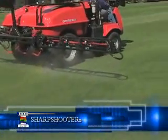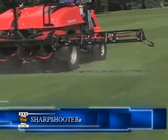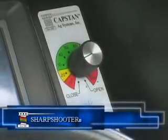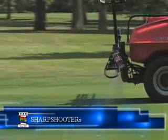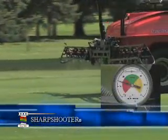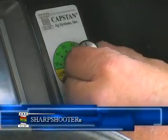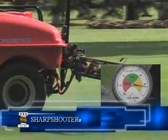SharpShooter utilizes drift reduction tips, but also affords the operator further on-the-go drift control. The operator simply dials the SharpShooter control to a lower pressure. The operator selected lower pressure provides bigger droplets and fewer driftable fines. The application rate and speed are maintained independent of this pressure change. Once the drift concern is passed, the operator can dial the pressure back to the original pressure set point for optimum efficiency.